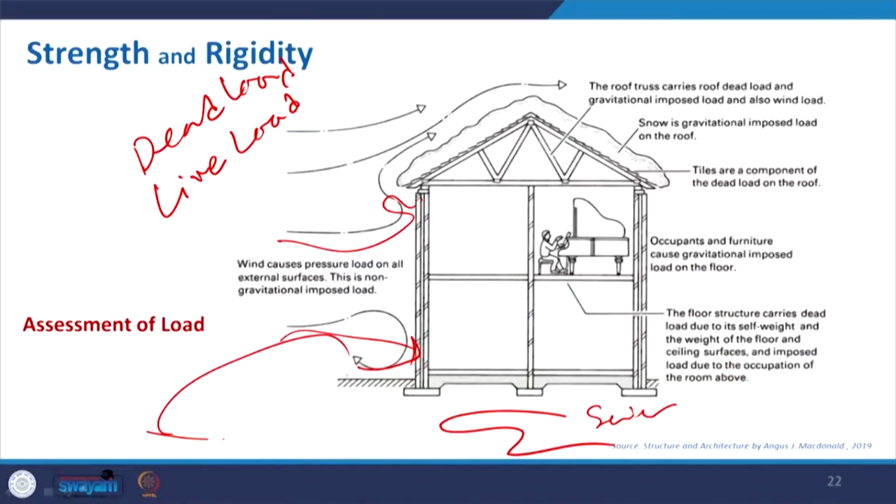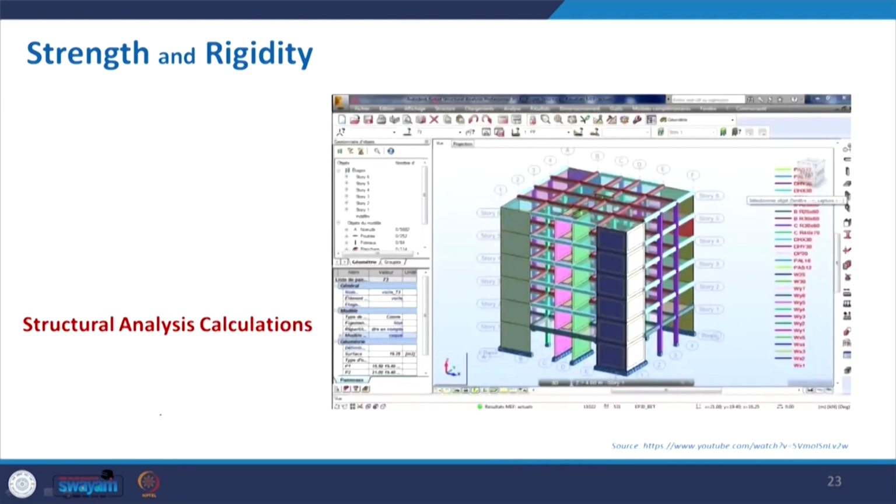Where we will make our building, based on that we take it, and if we want to make it in a coastal region where storms or the wind from the sea will be more prominent, we have to take some aerodynamic shape or size. So, depending on the structure, whether we go for a shell structure or maybe a frame structure, that is really required.